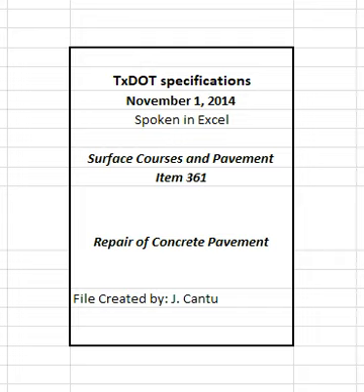Follow the epoxy manufacturer's instructions to apply the epoxy. Insert the tip of the epoxy cartridge or the tip of the machine applicator to the end of the tie bar hole, and inject Type 3, Class C epoxy to fill the entire hole. Insert tie bars. Place new deformed reinforcing steel bars of the same size and spacing as shown on the plans for continuously reinforced concrete pavement, CRCP, repairs.